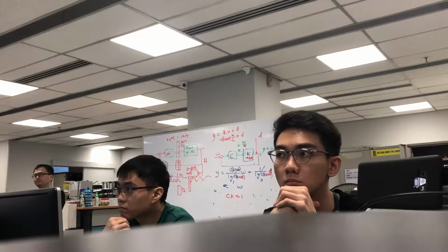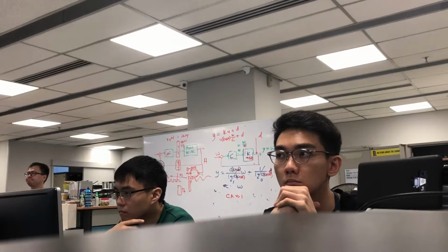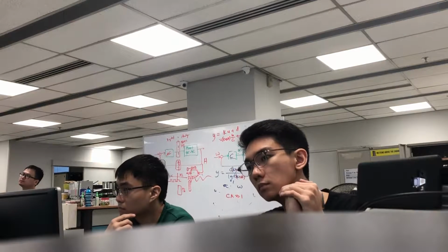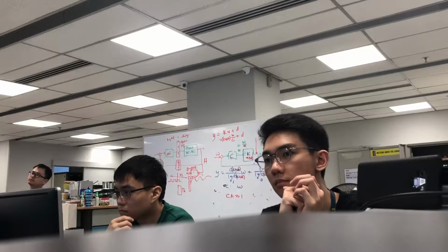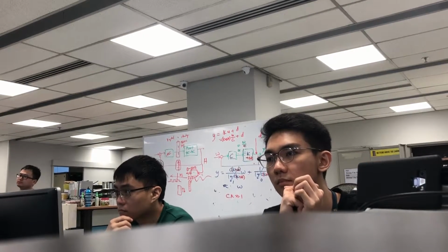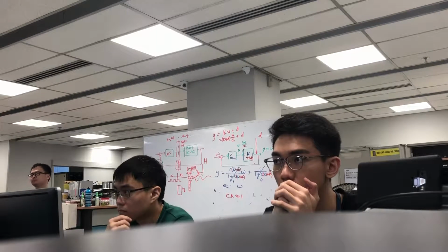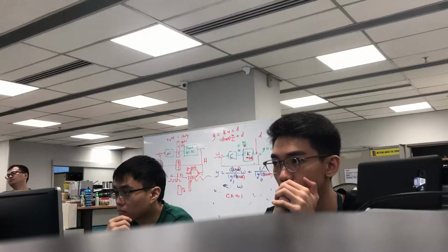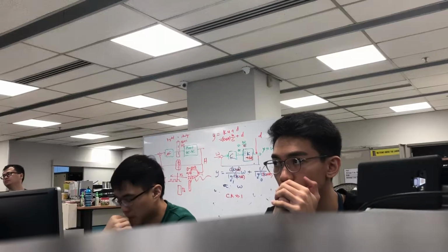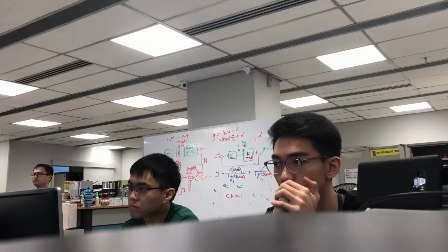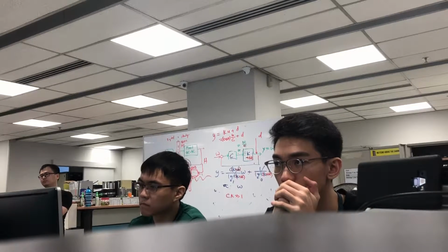So initialize the serial port at 9600 baud rate, and then you read from the analog channel A0 into a variable, and from there you print out the value. Print out the value and then delay for 100 milliseconds and repeat. So what's happening will be on your monitor through the serial interface. You'll be able to see those values that are read by the microcontroller. So this is how you do the ADC.